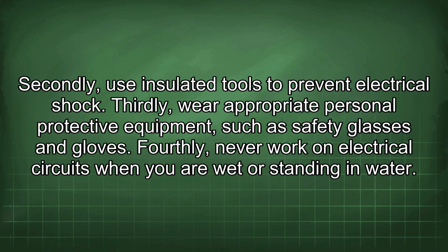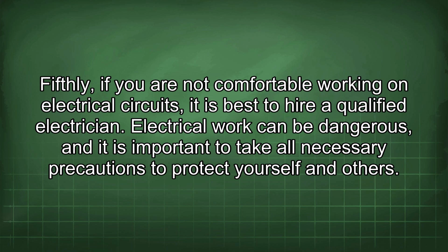Fourthly, never work on electrical circuits when you are wet or standing in water. Fifthly, if you are not comfortable working on electrical circuits, it is best to hire a qualified electrician. Electrical work can be dangerous, and it is important to take all necessary precautions to protect yourself and others.